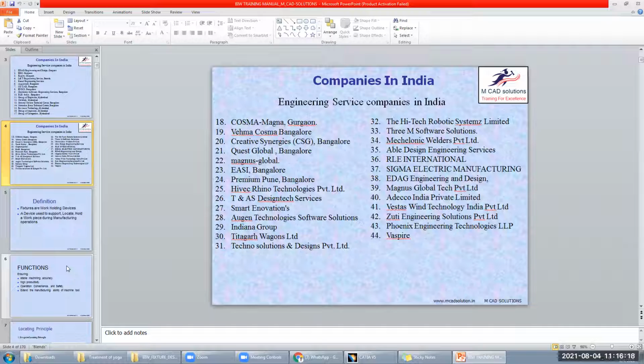These are the main two types. And we will check whether that welding tool, the welding gun, is working and reaching the destination, meaning where we have to take the spot. At that area, there should not be any parts. If there are parts, that gun or tool will foul with them. So we have to check the fouling and how much clearance is there. The clearance table or chart will be provided by the client or customer. At the initial level, there will be fouling and issues.